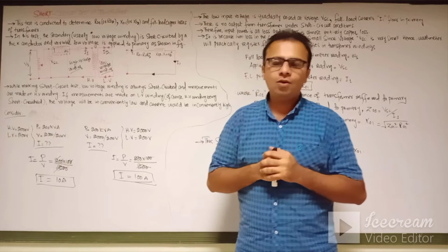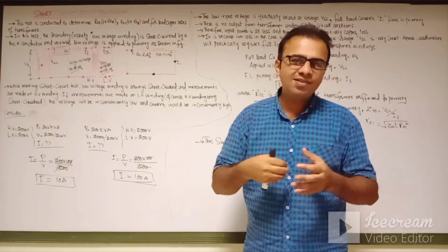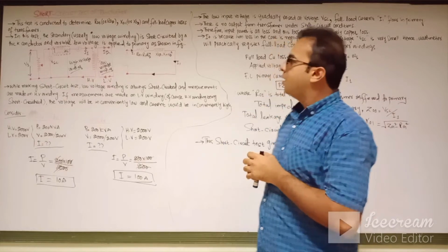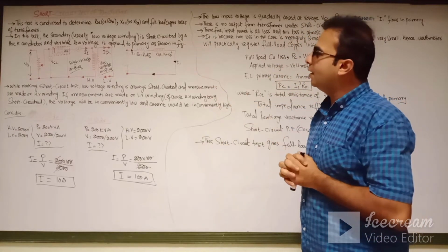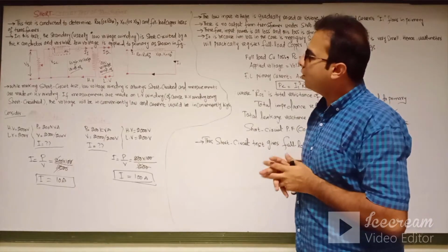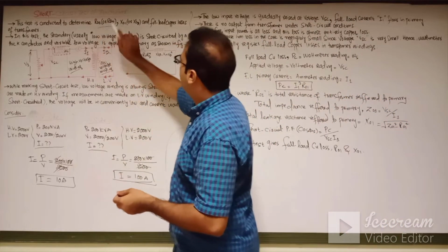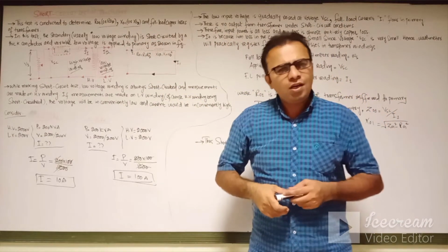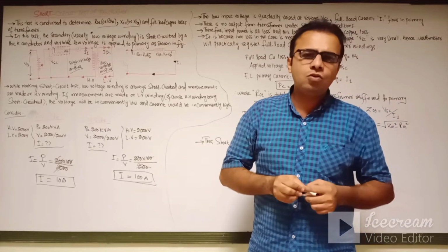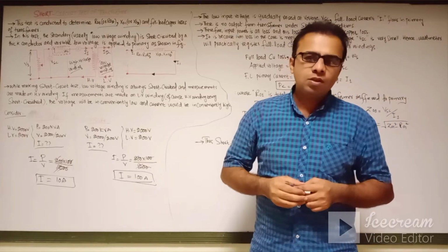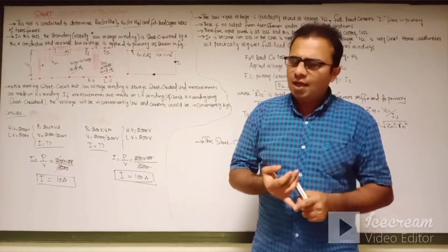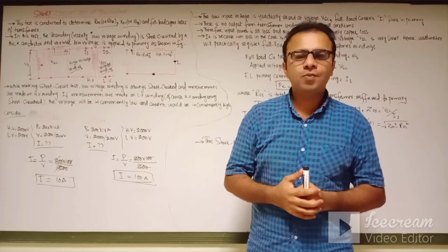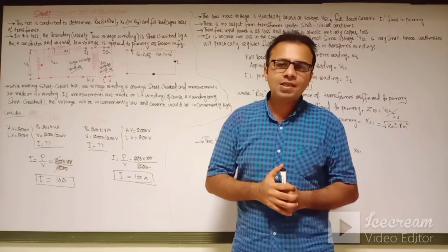The copper losses depend upon the ohmic resistance produced in the windings of the transformer. This test is conducted to determine R01, R02, X01, X02 and the full load copper losses of the transformer. To find the impedance in the transformer, we need the values of the resistance and the reactance components, and then we can easily find the impedance, because impedance is the combination of the resistive and reactance components.